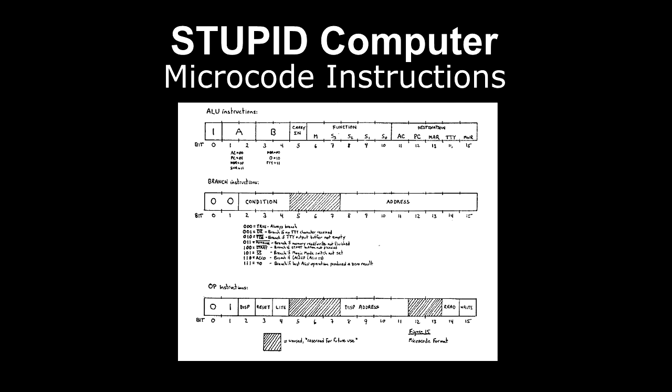ALU specifies a source and target register. Notice I did allow 2 bits for the B input, but again, I only implemented that as a 2-input multiplexer because that's what they would let me have. So I guess only bit 3 is used. There's a carry in. Now I said there's no carry bit, there's no carry register. But on the ALU, there's a carry in bit. And so if you want to increment a value, you're setting that carry in bit. The ALU is implemented with 74181 chips, which I don't think you can get anymore.